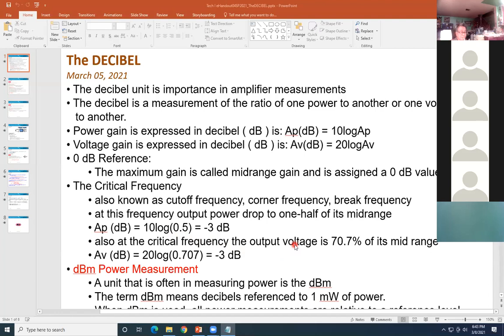You have to understand that this is a way of converting big numbers to small numbers. And you have to understand the law of exponents, because decibel is a power ratio. To convert a voltage ratio to a power ratio, because voltage or current is squared in power calculations, you have to understand the law of exponents. So I understand why people are very confused by this.